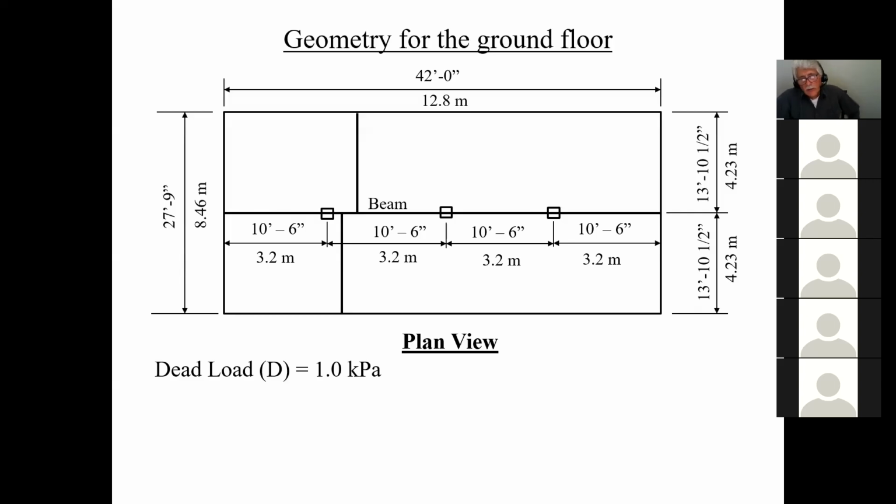And if at the end you're a little concerned about adding the weight of the beam to this, well, we can always go back and double check to make sure that the beam is okay, and I can show you how to do that. But you've noticed so far, guys, you go to the table, you look for an MR value of so much, and usually the MR value is slightly higher than what you need, and you look at the VR value slightly higher than you need, and so those slightly higher values can sometimes compensate for the weight of the beam.